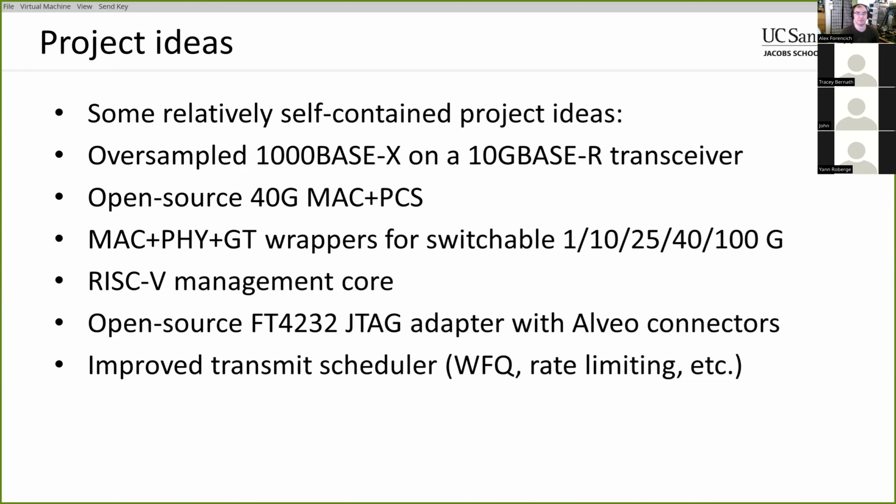So even if you have a device that also has a Zynq core available, which, I mean, certainly you could use that, or the internal... I would lean towards a PicoBlaze or something similar, right? That's all you need, just something to read some registers and probe some values, do some I2C. Right, yeah.